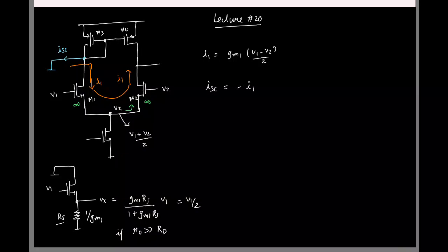That is where everyone is making a mistake here. See, how a current mirror works, you should understand what is the cause and what is the effect. For a current mirror, if you pump in a current in the branch where you have the diode connected voltage, that current is mirrored here, right? That works because the current here flows and generates the required gate voltage here, and that gate voltage in turn results in the current in the other branch, right? It is not as though if you pump in a current in this branch, it will result in the same current here. Only this works.